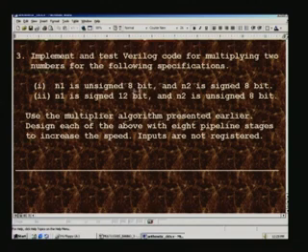One is 8 bit unsigned, the other number is signed 8 bit. This is an 8 into 8 multiplier, where one is signed and the other is unsigned, and which is signed is also mentioned here. Similarly, we need 12 bit into 8 bit. What we have seen in this lecture is 11 bit into 8 bit. Here it is different, and this is also different. We need both of these for our video compression algorithm, the DCTQ algorithm, which we are going to see later on, so be prepared when we come to that. By solving all these assignments, especially this and the 14 bit 8 numbers adder, those two are the ones which we are going to use.